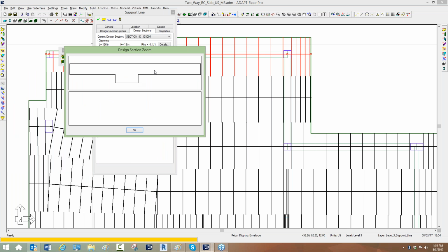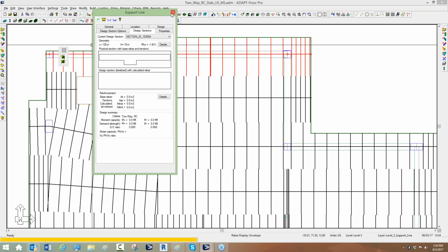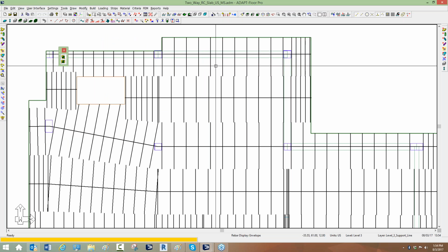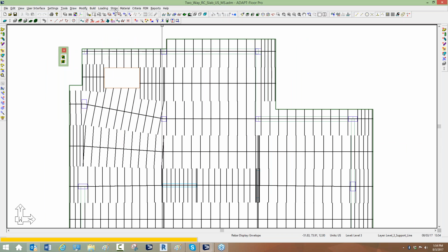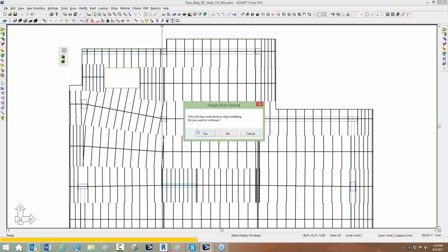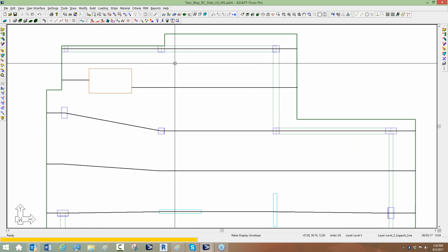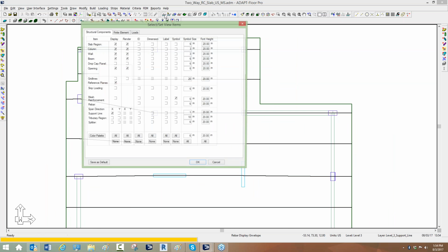and this is the physical design cut for that section. You say, well, I don't want to use that flange for the design of that beam. I want the beam to just be rectangular. So how do I tell the program, don't add a flange to this beam? In that case the user has to add those boundaries, those splitters.